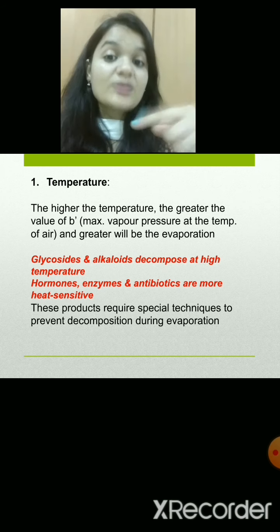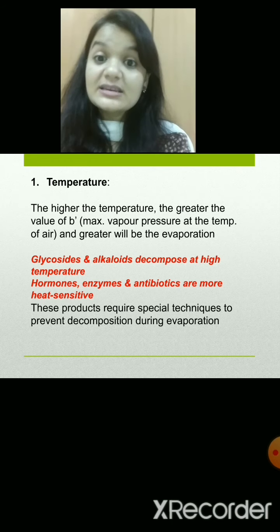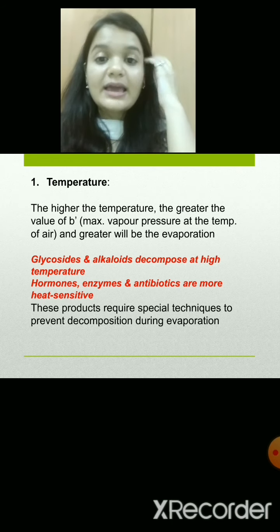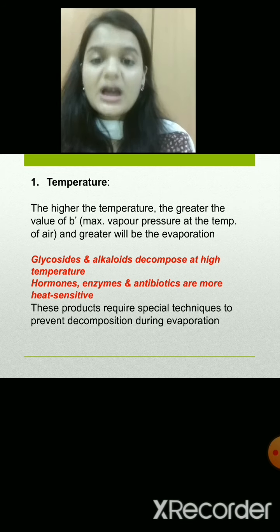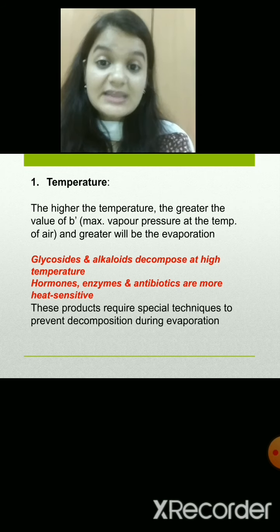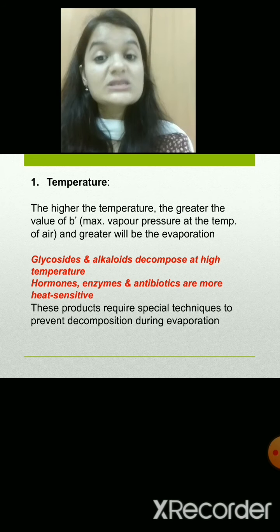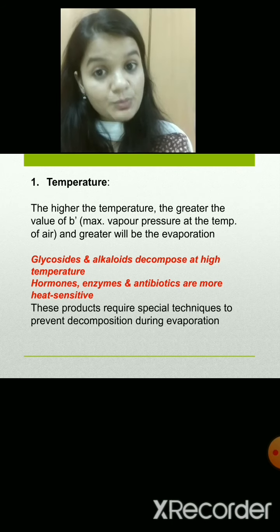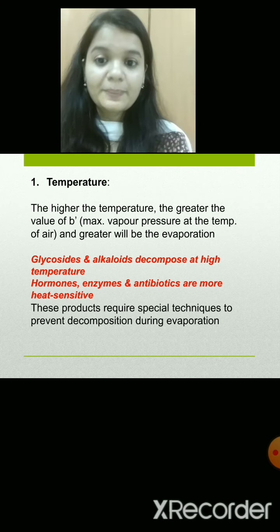But now when the temperature increases, some kinds of liquids, or you can say components, may get degraded, right? Like enzymes, hormones, antibiotics, or some plant components like glycosides and alkaloids. So you need to design or use specialized evaporation processes to prevent the decomposition of such products, right?